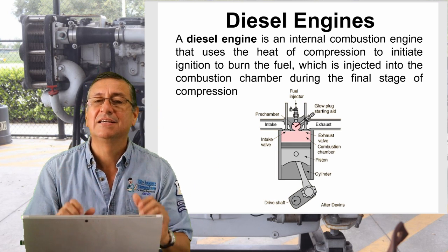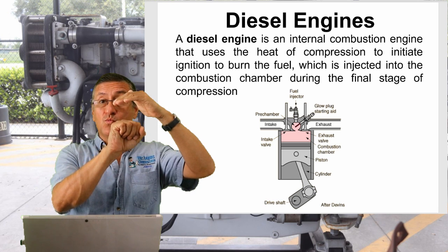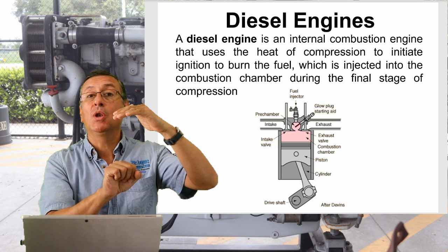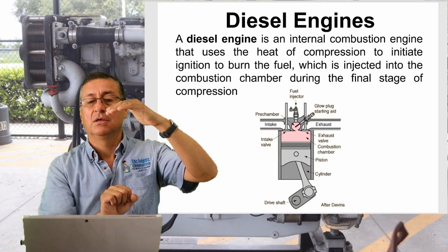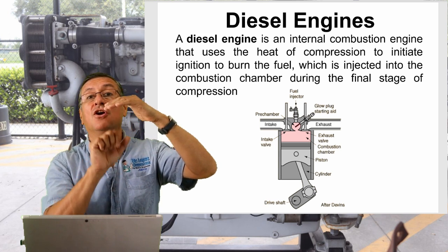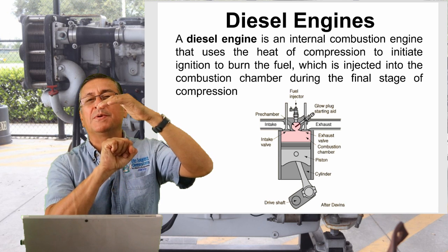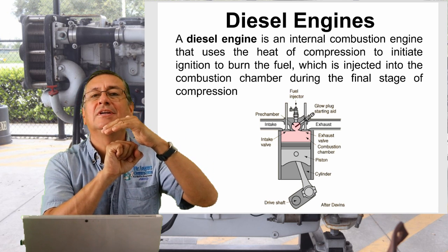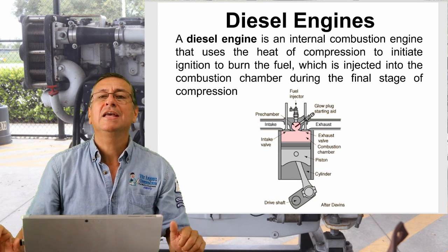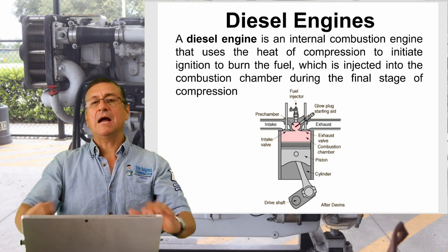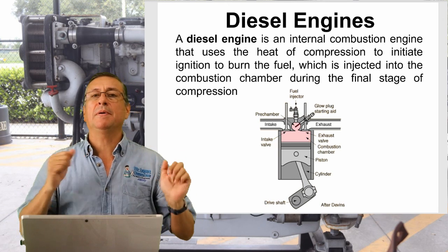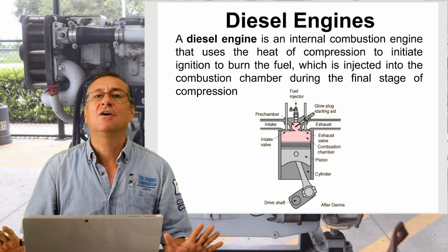This is in gas. Once again, the piston goes down, the intake valve is open, and air and fuel enter. After that, the piston goes up, the valves close, and the piston compresses the mixture. When the mixture is fully compressed, the spark plug ignites the mixture and produces the explosion, and the piston goes down at higher speed and continues the cycle. This is in gasoline. That's clear, my friends?